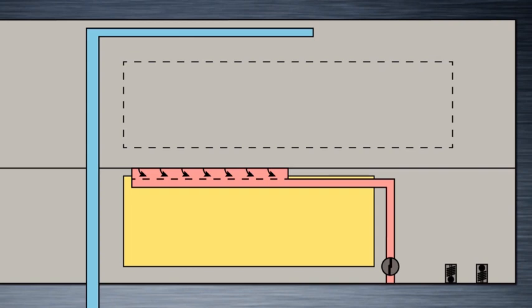Early on in the lesson, we mentioned that the cabin pressurization system has a relief mechanism that is provided as a protection mechanism in case the pressurization system were to fail. Two relief valves protect the cabin from overpressurization and negative pressures. Two positive pressure relief valves, located aft on each side of the outflow valve, protect the cabin from overpressure.